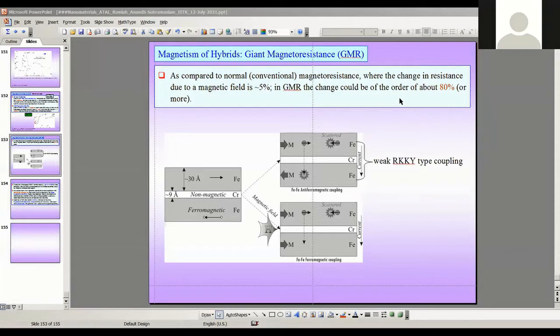Now, when you keep on reducing the size, at some point you would expect that the strength would be so much that it will go above the theoretical shear strength. So what is the theoretical shear strength? It is where the material can just shear, where the whole atomic plane can shear over the other.